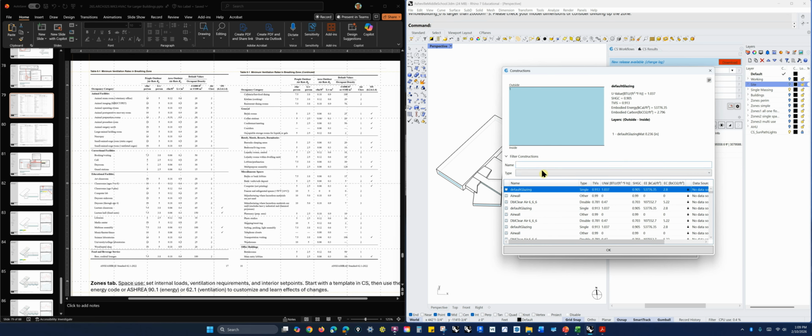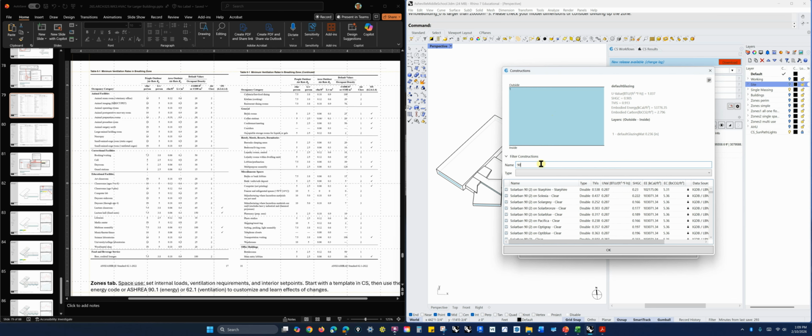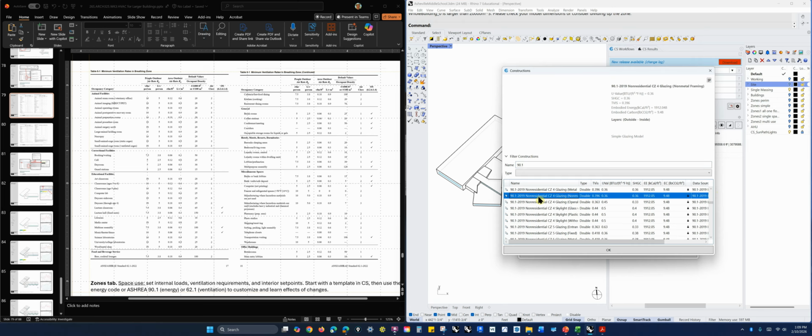Let me click on it. I'm going to type in 90.1. Oops, I didn't mean to hit enter. 90.1 non-residential, climate zone 4. Not skylight glazing, non-metal. Let's just pick that. We see that, and if you look it up in the code, these are basically the bare minimums for U-value, solar heat gain coefficient, that's the maximum solar heat gain coefficient, and TVis, that's pretty low, 40%.